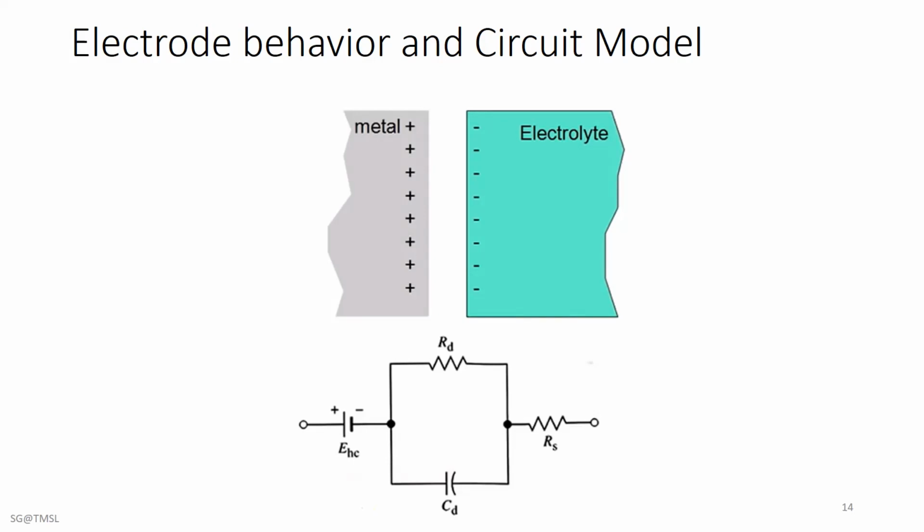Sometimes this is a single electrode electrolyte interface diagram, but most of the time we need two electrodes at the same time, because one electrode is not sufficient to measure or monitor the actual biopotential with the measuring device. When both electrodes are of the same material, the electrode offset voltage must be very small. If both electrodes have different materials, the electrode offset voltage is also significant in this case.